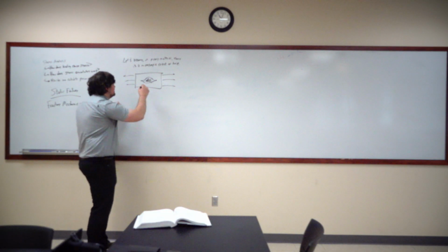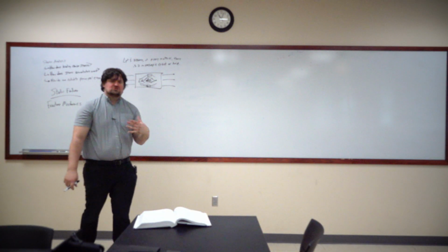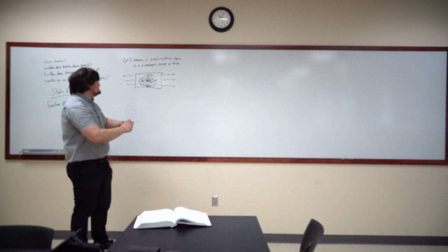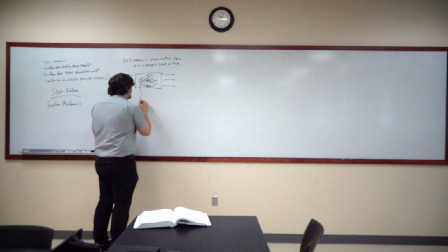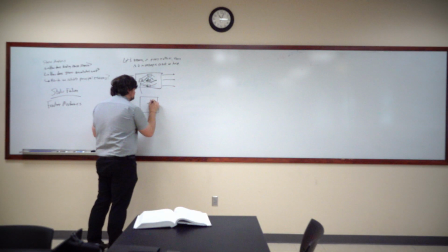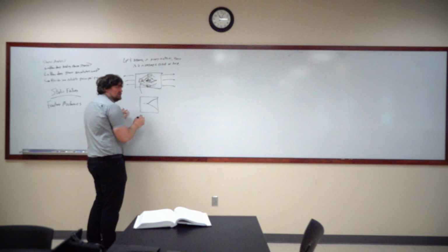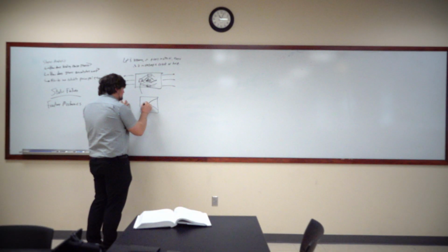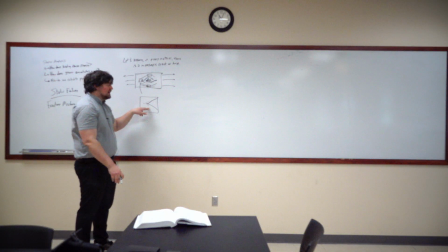So what we have is that the load ends up having to kind of go around this system, and it leads to stress concentration here, here, and there. And that stress is substantial. Now, as we pull on this, what's going to happen is that because of the stress concentration right here, if I go ahead and bring this piece out, because of the stress concentration here, when I apply a load in this direction, it's actually going to pull this way, it's going to pull this way, and it is going to want to pull that crack apart. It's going to want to grow and propagate that hole.